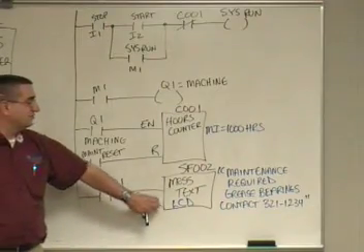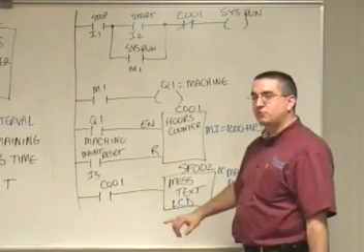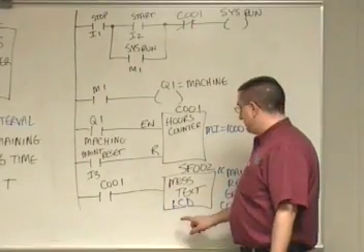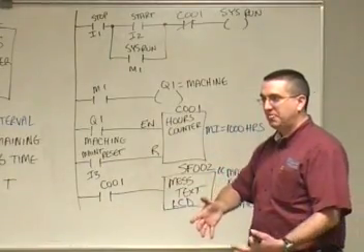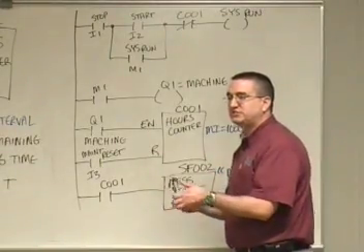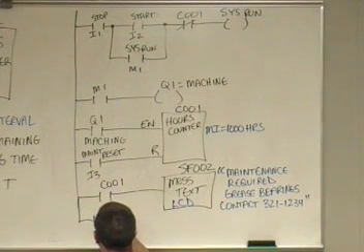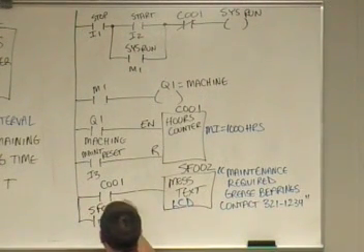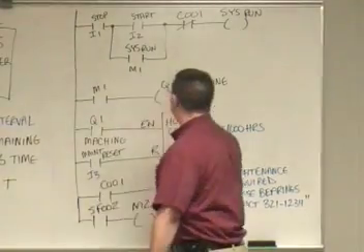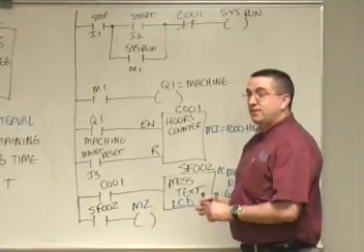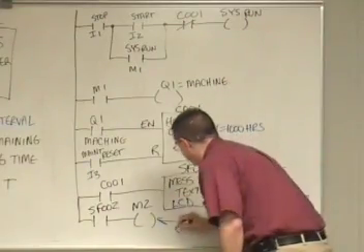There's one thing about using the message text that's vitally important that you're going to discover in one of your next jobs here. The message text requires a flag output. Anytime you use this message text, the very next line should have a contact associated with it, what I call a message text flag. The reason why is very, very important.